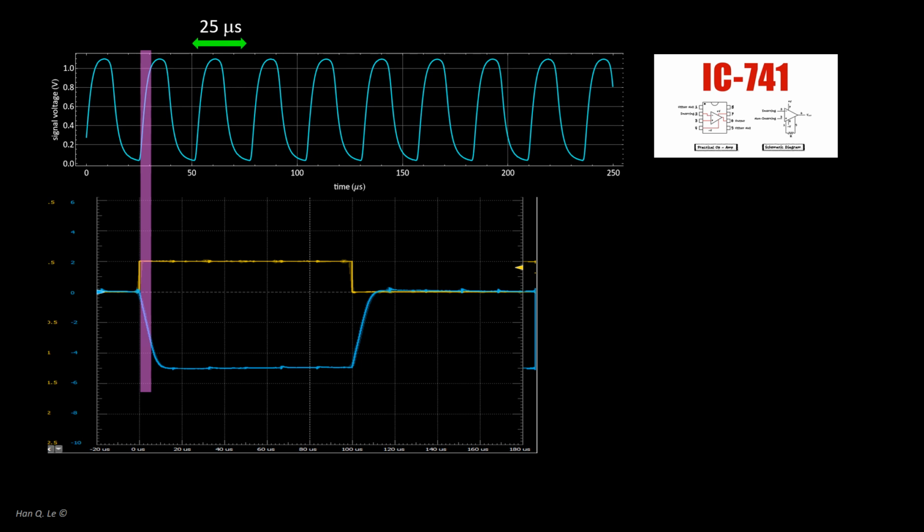Nevertheless, this comparison once again confirms that the limiting factor in time response, and hence bandwidth, is the speed of the 741 op-amp, which is the slowest of all op-amps, and in fact is often referred to as a dinosaur op-amp in the electronics hobbyist communities.